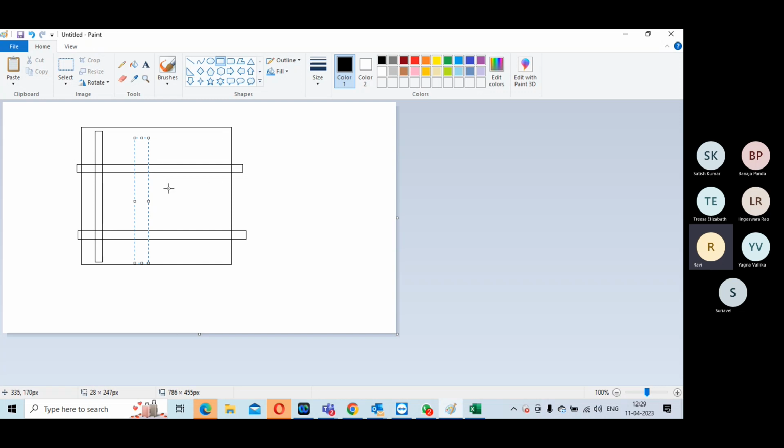Yes, power domain. So here what you will do is add a power gater. This power gater has three signals. One is called the sleep signal. This guy will have always on power connectivity, but it will have an output power port. Whether current is flowing through this or not will depend on this switch logic.